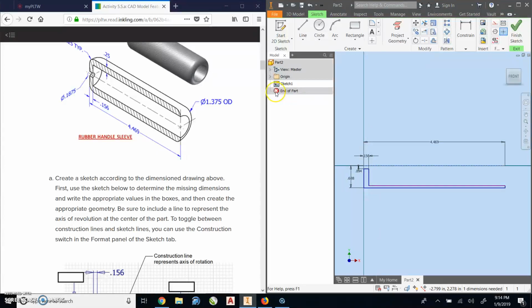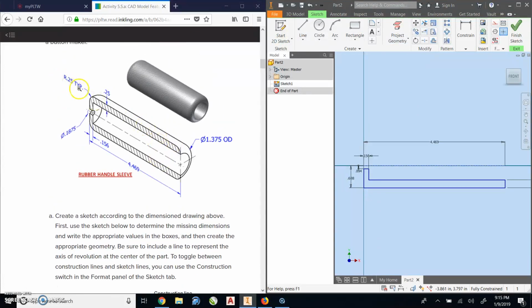And finally, what I need is the overall thickness of this piece. So that looks a little wonky right now, but my overall thickness of this section is 0.25. So it's going to get cleaned up by clicking the two lines, bringing it to the side. Notice right now it's 0.06977743. We are going to make this instead 0.25 and hit enter. So that shifts everything into place. It is fully constrained. If you wanted to, you could add the fillets at this point. The 0.25 typical fillet. I like adding fillets in the feature, so that's what I'm going to do instead of it being in the sketch.